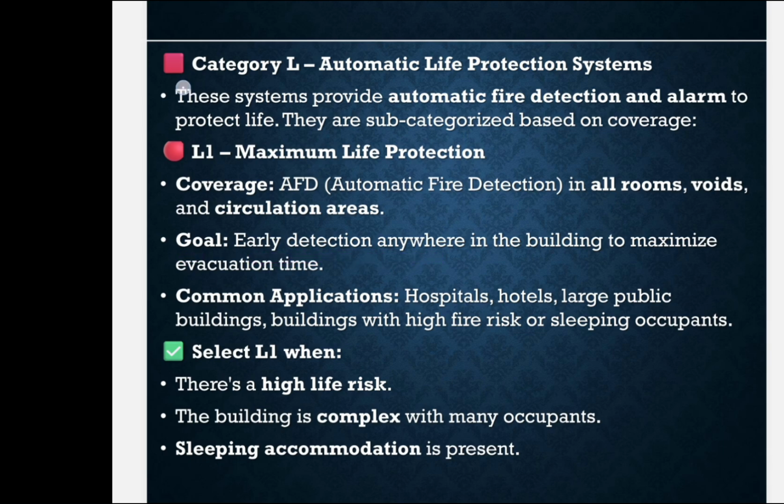We can use this L1 fire alarm system in places like hospitals, hotels, large public buildings, and buildings with high fire risk and sleeping occupants. So wherever there are occupants sleeping inside the building, we have to go for the L1 fire alarm protection system.